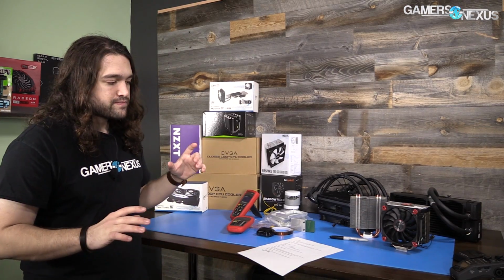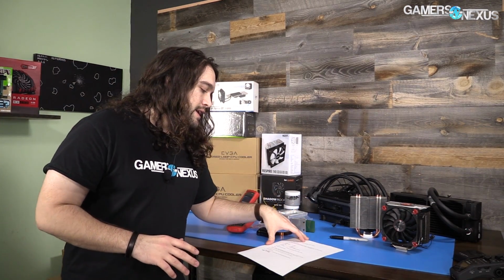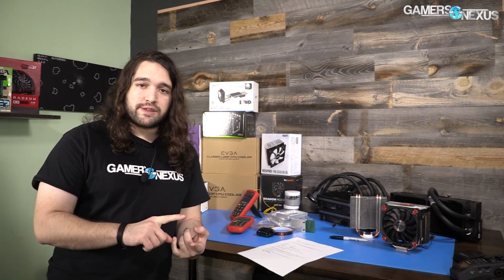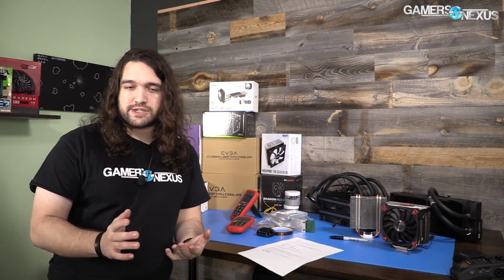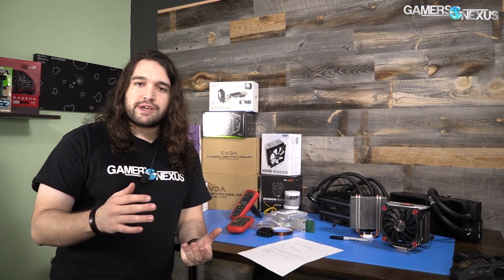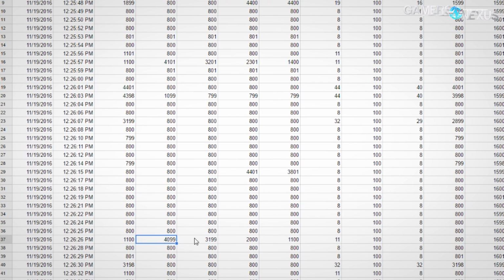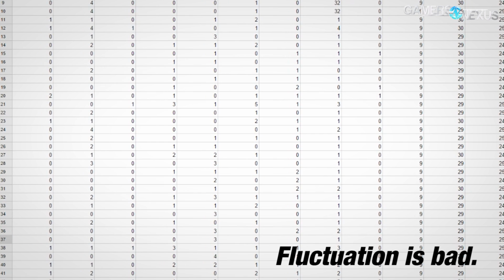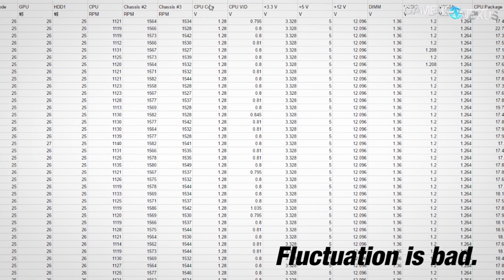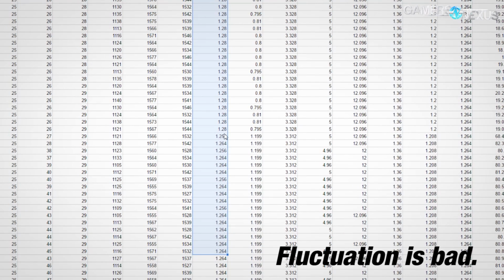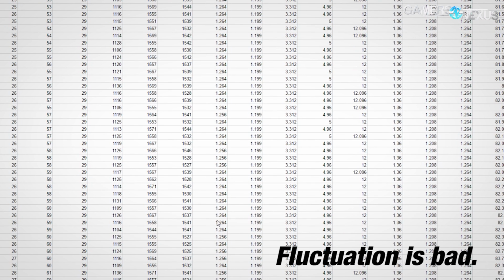The reason for that is because an Intel CPU says, I am going to boost as much as possible when thermals allow and when voltage and power supplies allow. So let's say the CPU is boosting. Occasionally, you might have V droop, whether that's from your voltage and power supply chain, or you could have just a frequency drop and voltage change up or down based on whatever's going on with the test process. And then, of course, AVX instructions also can really change things. So make sure you understand what those are too, if using Prime 95 or something like that.